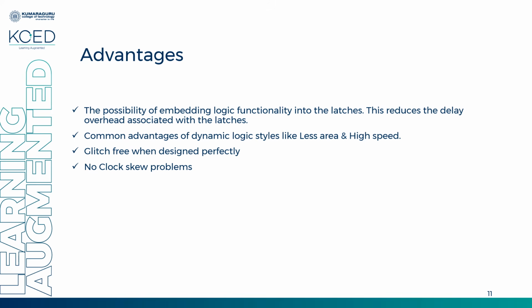You can design logic. Now all the common advantages that are applicable to a basic dynamic logic cell will be applicable here also. And when you design properly, with more clarity, you can have a glitch-free system in the case of TSPC. And very importantly, no clock skew problem is present. The only disadvantage you can mention is that in certain cases you will have more transistors, and when you go for a simplified TSPC, the strong 1, strong 0 problems are revisited here. So that's all about your TSPC logic design style.